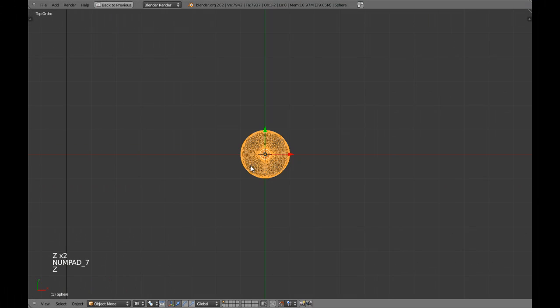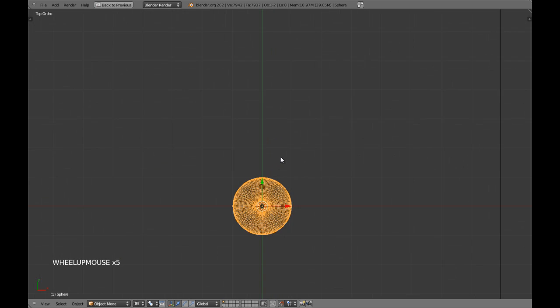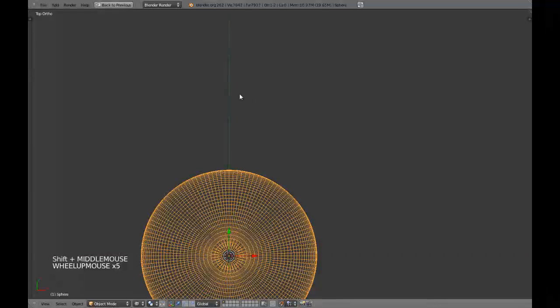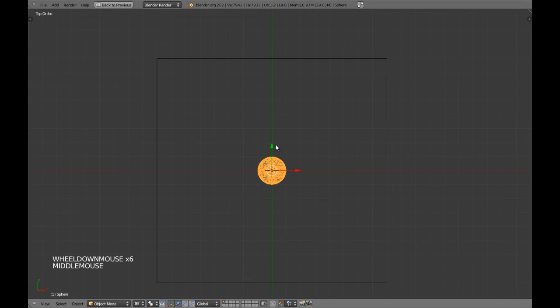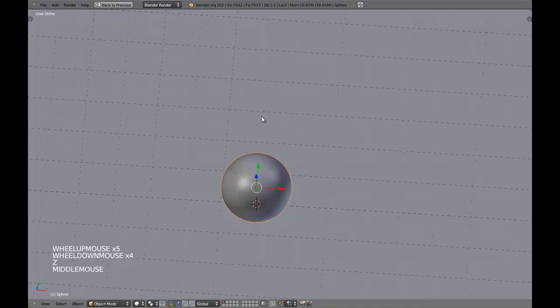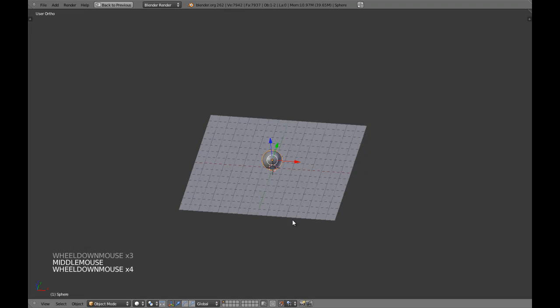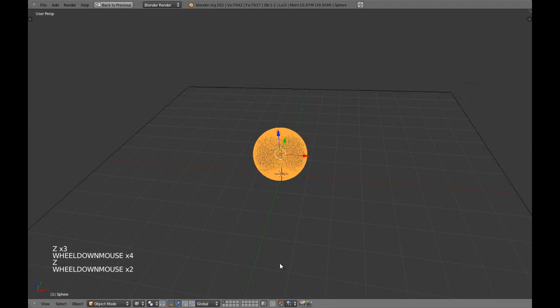if you are from, let's say, top view, you have these grids, these cubes here, and if you get closer, you will find that there are a lot of cubes inside those cubes, or inside the squares, because there are no cubes. So that's how Blender uses the increment snap to move.